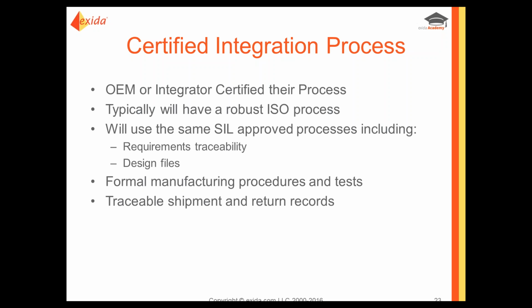Then there would be some additional steps. Depending on the complexity, they might have to trace the safety requirement specs down through the final element, and might need to do a simple FMEA to identify safety critical and not safety critical parts, and do verification calculations. So it's not completely covered already, but they're a fair way down the road. None of this in the standard says you must have a third-party cert. It's basically that you need to be able to show the evidence. So process owners could do these steps themselves as well.